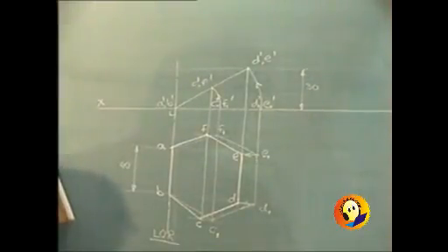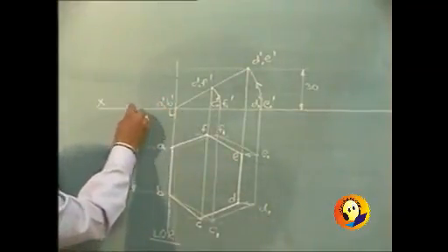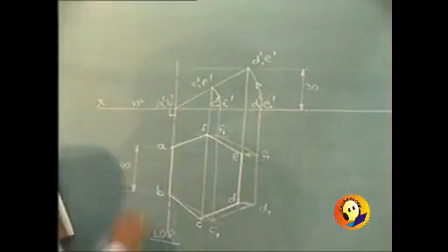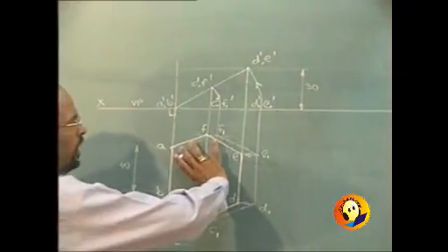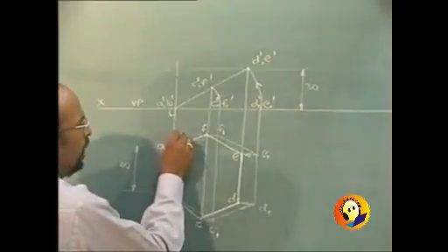Now in the problem it is stated that the side which is in HP, in our case side AB, was drawn perpendicular to the vertical plane initially because it was the line of rotation, but in the problem it is stated that it should be parallel to VP, so we are required to rotate this new plan such that AB becomes parallel to XY line.